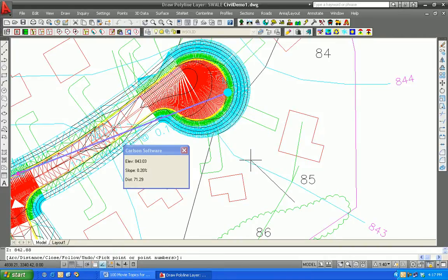And then what you can do is take it on down into the edge of your shoulder. See, I'm going to go down here at roughly a 3% grade. See how it's negative 2.98%? I'm going to pick a point,